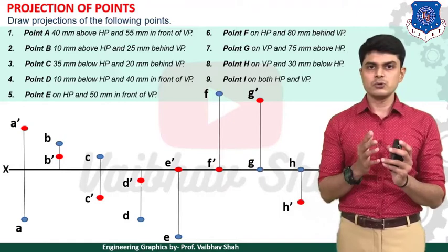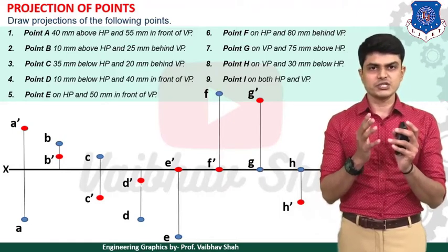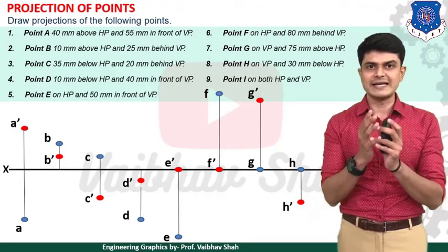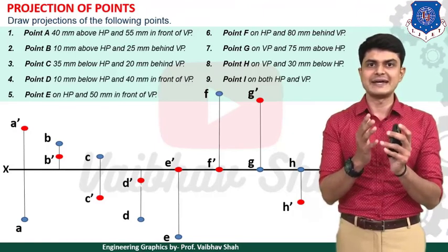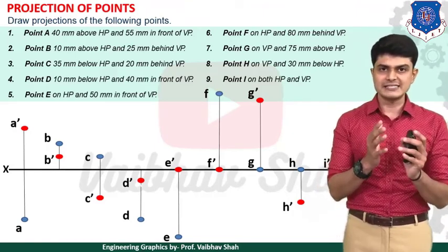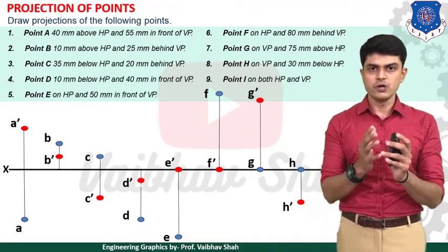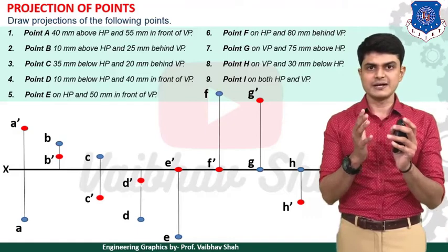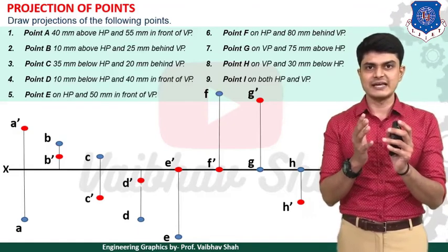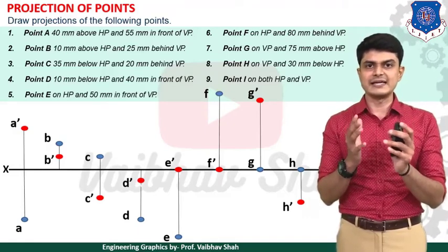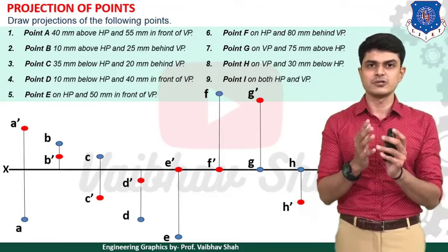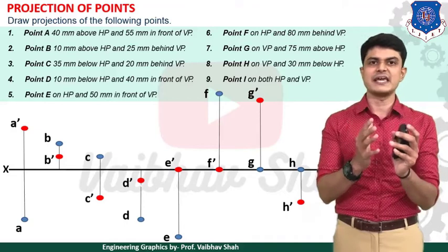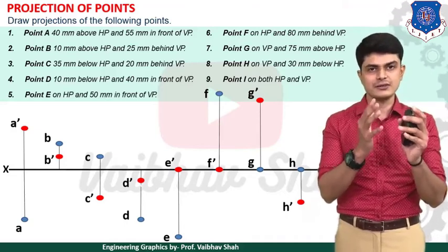And you will have point A in blue color. Here our chapter is projection of points, which means you need to highlight your points with a dark point, and the lines connecting these points should be as light as possible. So in this example, you need to draw your XY line with normal darkness, and darken the points A dash and A a little bit more. The connecting line should be as light as possible, because it is a reference line showing that the projections A dash and A lie on the same vertical line.